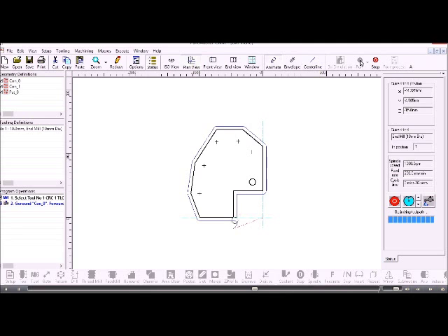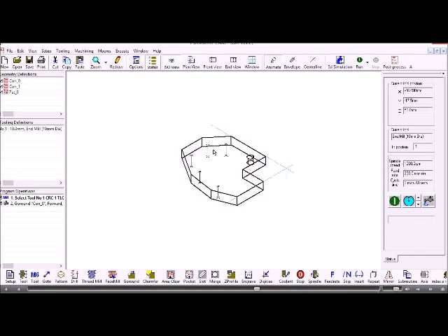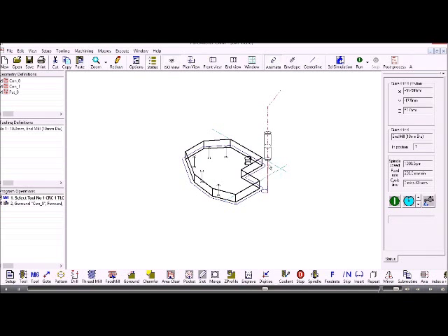So that's moving the tool around there. If we view in the isometric view, and again we just zoom in and zoom out using the mouse wheel, and then we run the job. So the tool starts from the home position, rapids across in X and Y, rapids down to the feed change plane, which is 3 mm above the job, feeds down to the depth, applies the arc approach, machines all the way round, and then applies the arc runoff, and then retracts back to the clearance plane.